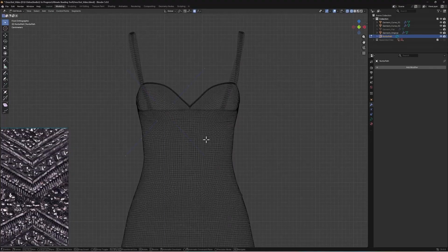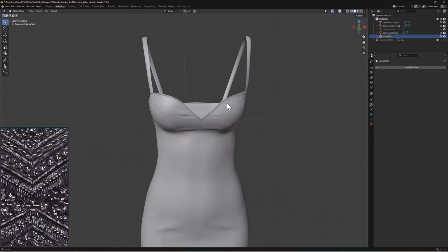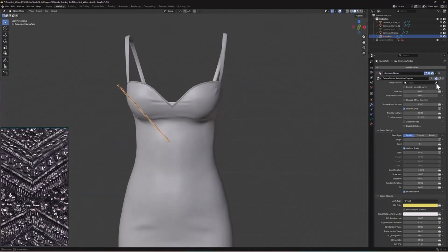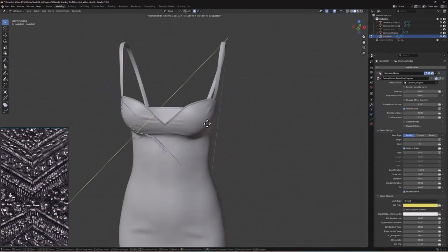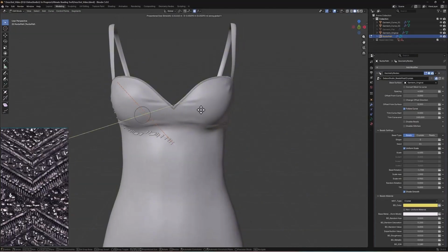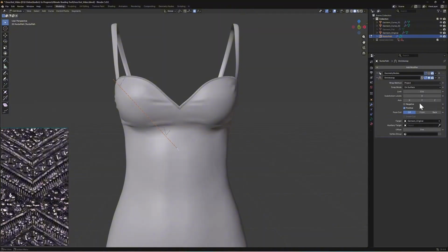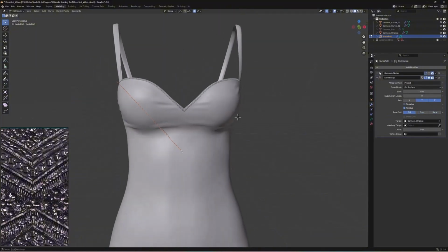The tool does the projection by nearest surface point, but in some cases we need a more precise workflow. I use the shrink wrap modifier and use project in Y-axis. Move the curve if it's needed. Now I have a curve to start with. Apply shrink wrap and use it again if you need it.